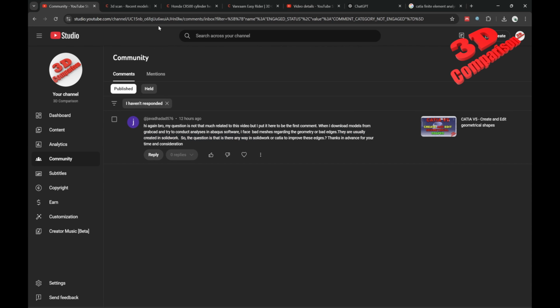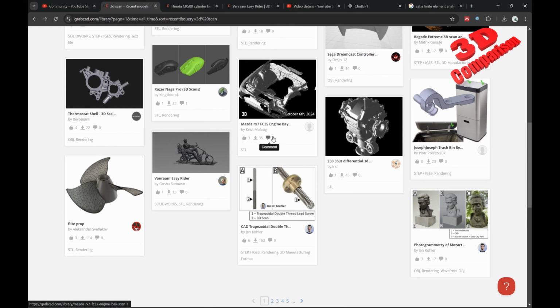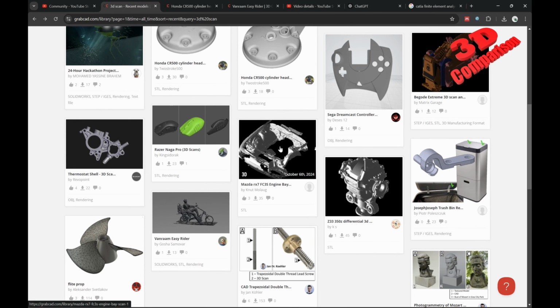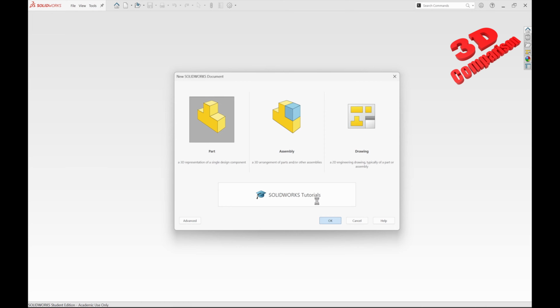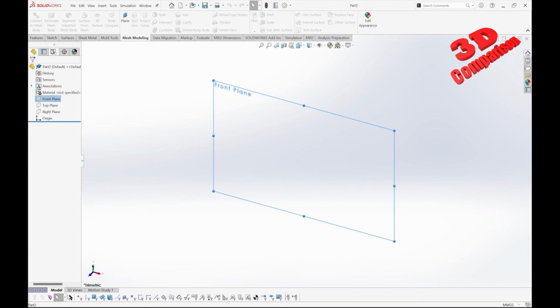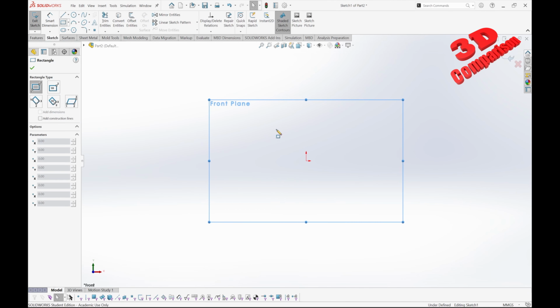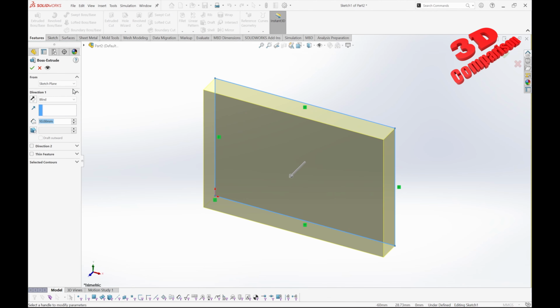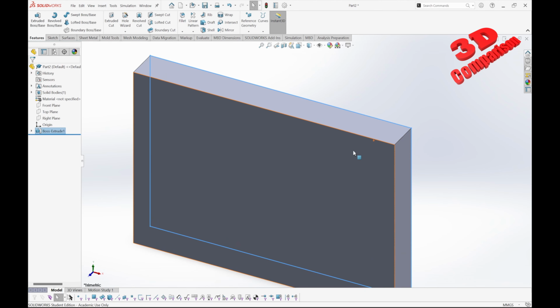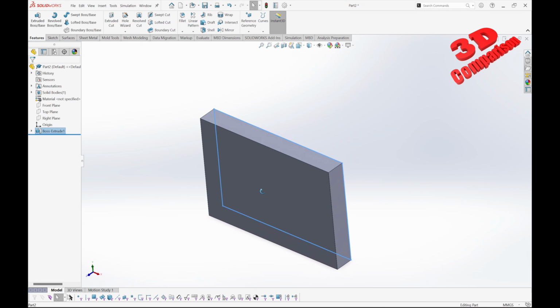Now let's take a look at this. Initially I've searched for some 3D scan over here, because usually models that are created directly within SolidWorks shouldn't have any problems, because those will just convert afterwards easily. So everything that is being modeled over here will be converted into a mesh that can be used for those analyses.